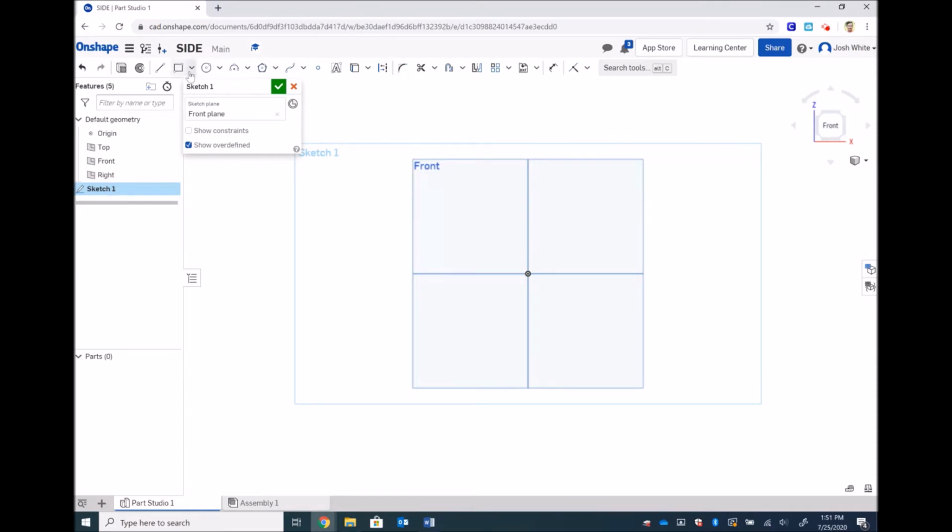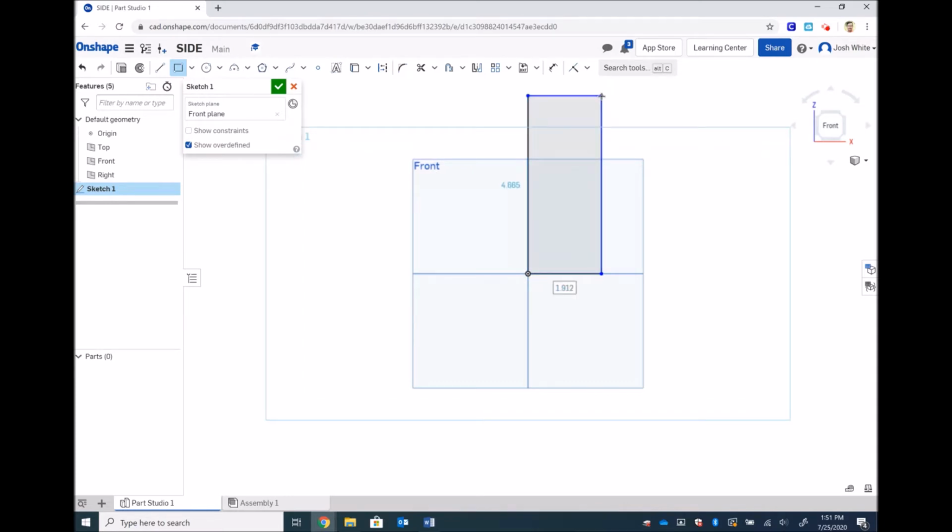I gave dimensions in our drawing, but moving on to our front piece and our roof piece, we are going to need angles to make that slant line up for all the pieces. So we're just going to make this a 10-inch by 3.5-inch rectangle. Our bottom text box is open first, so we'll make that 3.5 inches. And whoops, let's make our side dimension 10 inches.